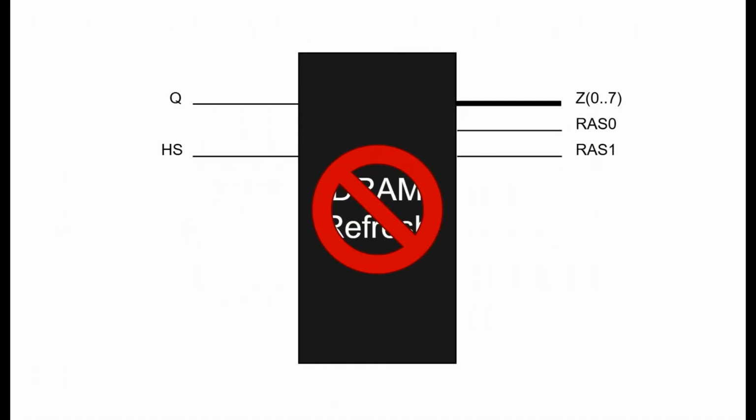If I'm only specifying SRAM, then I don't need the multiplex RAM addressing. I should just need the main address bus, and this is almost true. The fly in the ointment is the P register. This single bit register can have control over the most significant bit of the address bus when specifying RAM in the mixed RAM plus ROM memory mode. So I need 1 bit of Z at least to replicate this behaviour.